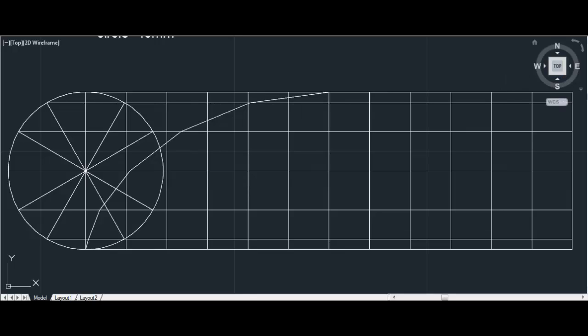For the next part of the curve, I'll use the mirror command. You'll find the mirror command on the right side of your AutoCAD. I'll select the objects that I want to mirror, and specify the first starting point, and it's done here. So I have got the other part of the curve also. This is the locus of the lowermost point for a complete rotation of the circle.